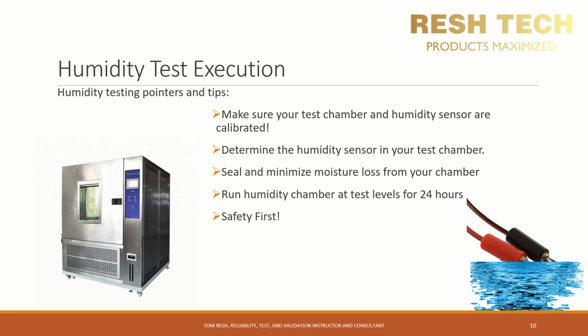Also consider safety factors as well. Don't have electrical cables sitting on the bottom of the chamber where condensation and water can accumulate, as you can cause shorting or even electrocute yourself or someone else who goes into the chamber to check on your test units. So don't be an idiot and play it safe.